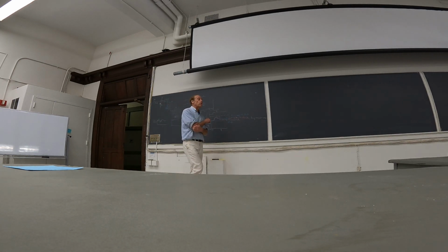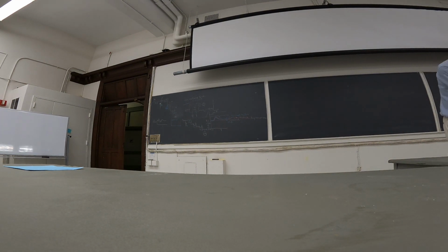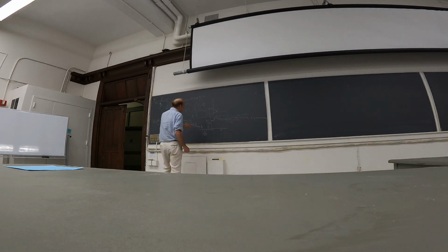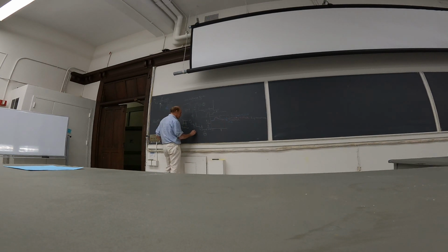We have to go pretty far away from where we want to be before the feedback really kicks in. So one way of trying to remedy that, again, this is control strategy, might be to add what's called feed forward. So for example, we said that there could be a problem in the input. So if I measure A in the input, then I will immediately notice that there was a problem in A before I get to the output. So if I do this, then I can also have, and this part is feed forward. This is feedback.